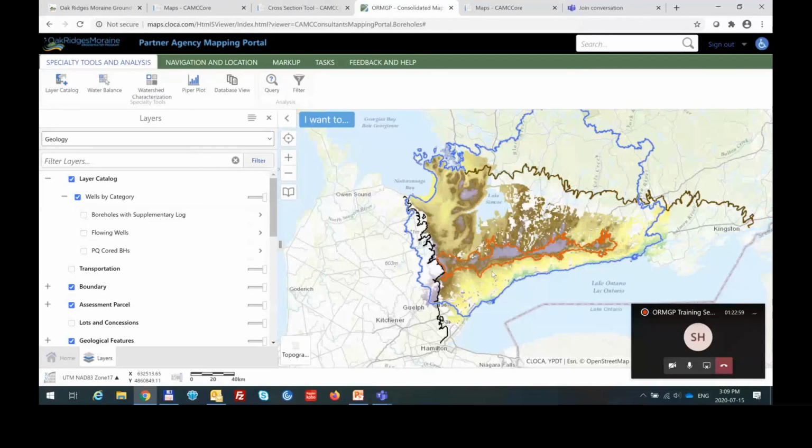That could also be us having available low flow stream flow survey results where we see gaining reaches and by how much flux, because those correspond to cold water fisheries as well, where we have large discharge or gaining reaches from the low flow stream flow surveys. Right. Where people walk the whole stream and map the flow at various locations, remote from storm events or rain events or snow melt events, and you can get an idea of where streams are gaining groundwater discharge.